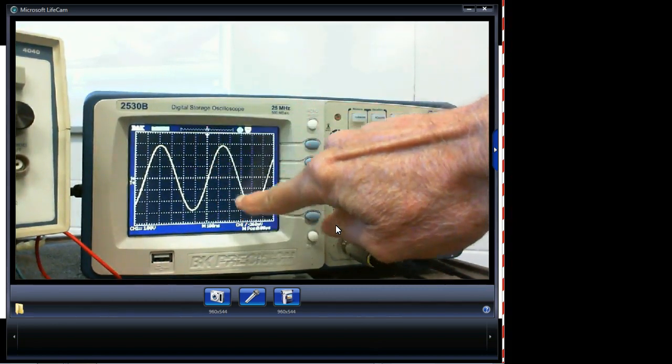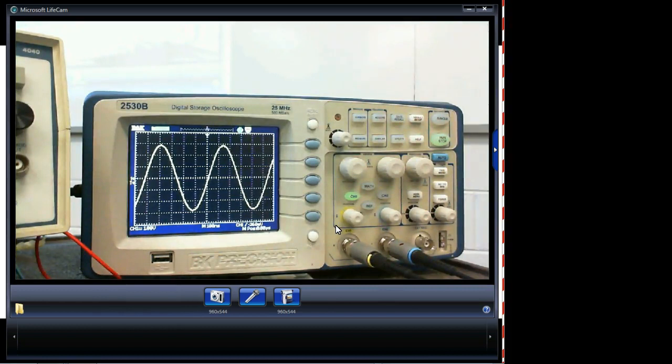But what does the oscilloscope measure? It does not measure RMS, it measures peak to peak. I understand that. So if I had the RMS value and I wanted to see how that would look on the oscilloscope, then I would have to convert from RMS to here. A lot of times we'll see we need to go from the scope over to a meter. Now the meter's going to read a lot less, right? You understand that? Yes or no?